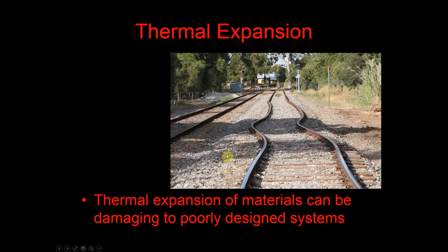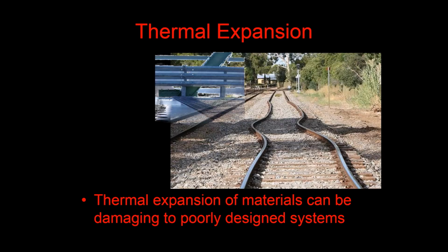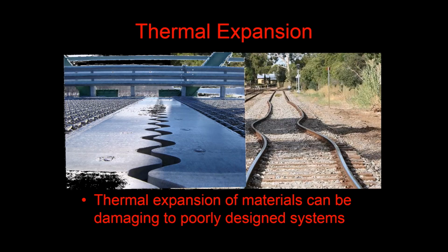And that's when we referred to our thermal expansion. The reason that we put these joints in is that the stress these tracks are actually under is related to that particular value that we just looked at. And if we put a thermal expansion joint in here to allow these tracks to expand and allow these tracks to contract, then they won't actually buckle as they have in this picture.